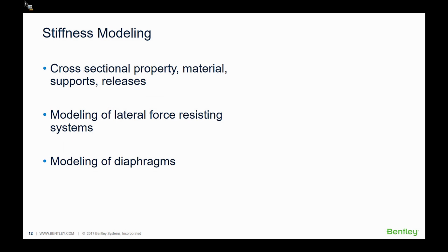Modeling of diaphragms is also very important from a dynamic analysis and lateral load analysis standpoint. Rigid diaphragms may be modeled using the floating diaphragm option in STAAD Pro. This ensures that the torsional effect due to the eccentricity between the center of mass and the center of rigidity is accounted for in the analysis. If you have flexible diaphragms, you should model them using a mesh of plates.